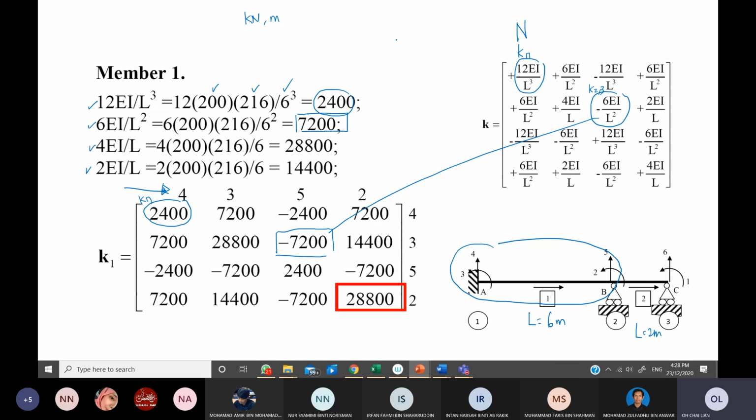Okay, in this beam, we have vertical and also the rotation. So you name the Y direction first, then only the Z direction. Therefore, here you can start with NY, then you name NZ. N means near end. Then you go to far end at the Y and the far end at the Z. F is far end.